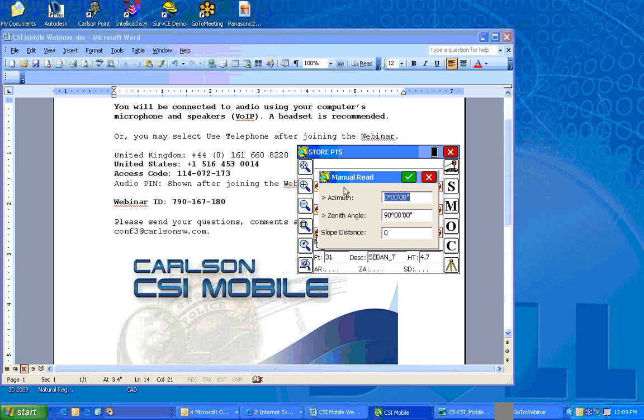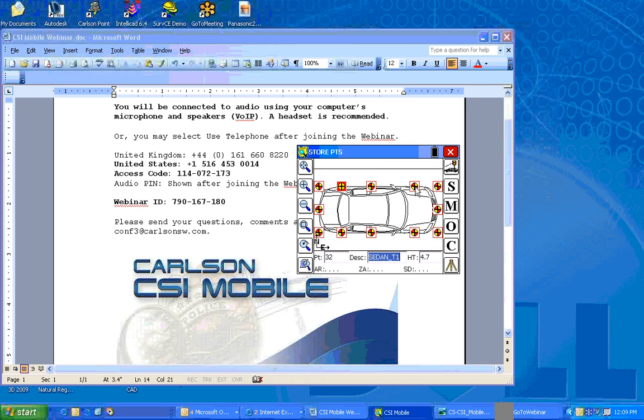By the way, you can set it up to angle right or azimuth. Many police departments like to work azimuth. So I'll do an azimuth of 345, and I'll go a distance of 40 feet. And then this next shot is for the direction. It will not dimension from this shot because it knows the dimension of the vehicle. So if you can go to the front tire, it's only going to be used for the direction and orientation of the symbol as plotted.